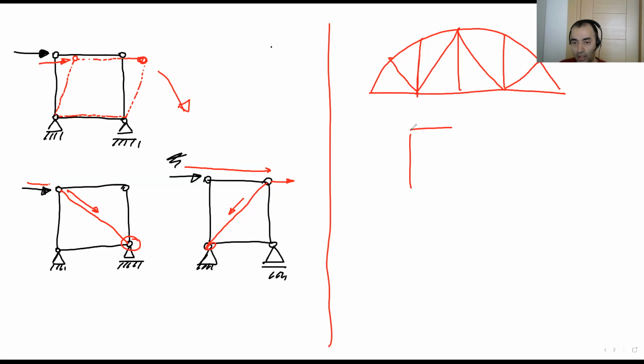If you have a square, every edge equals the others. Again, we need a bracing member. So we need triangles. We have straight members. The two ends of these straight members are hinges. Okay, hinges. There is no moment at these ends. That's okay. We need triangles to get stability.